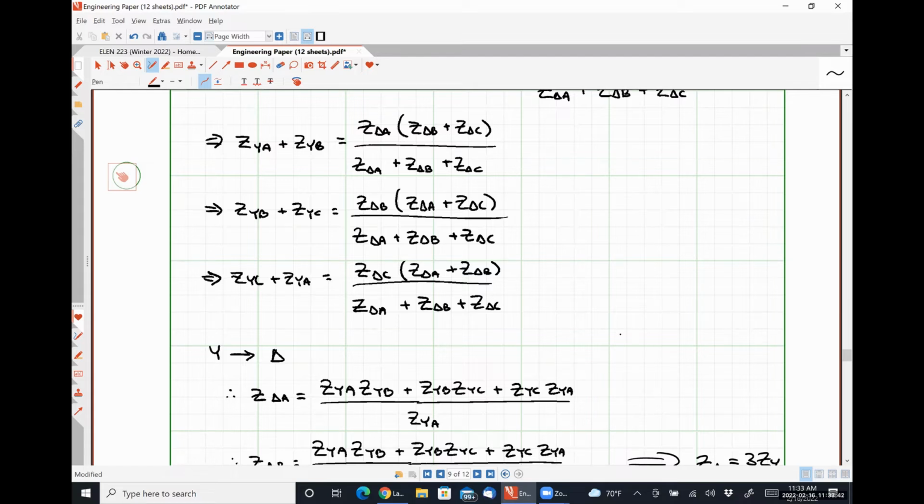They are equivalent loads, okay? Electrically equivalent, which means they should be consuming the same amount of power. So they're going to mess with the voltage and current relationships in a particular way to satisfy that. Does that make sense? The whole point of electrical equivalency is that it has the exact same terminal voltage, the exact same currents, and consumes the exact same amount of power. If those aren't true, they're not electrically equivalent. You can have bigger individual loads to make up.